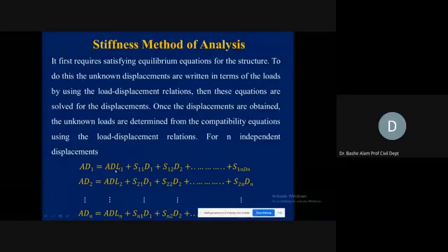determinate structure due to load. यहाँ पे आप क्या देखेंगे, वहां पे आप डिस्प्लेसमेंट को कैलकुलेट कर रहे थे, यहाँ पे मेंबर एंड एक्शन आप कैलकुलेट करेंगे। Instead of the displacement you will be calculating the action now corresponding to the displaceable joint due to the actual loads. वहां पे आप F11 कैलकुलेट कर रहे थे, यहाँ पे S11 कैलकुलेट करेंगे। S11 कैसे कैलकुलेट करेंगे, it will be the force required to produce unit displacement। So क्या करेंगे हम, we apply a unit displacement and find out the corresponding actions। D1 क्या है, वहां पे AR1 था, यहाँ पे आपका unknown joint displacement आ गया। Similarly S12, D2 and so on.